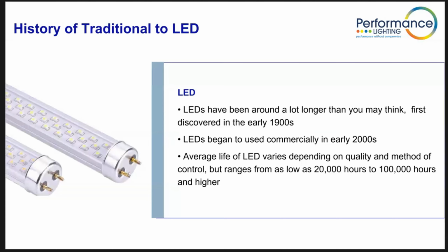A slightly new feature, and we won't really touch on it today, in relation to colour temperature, is tunable white, which means you can actually change the colour temperature. It's one LED, and it can go through the colour temperature normally from 2,700 to 6,000. So that's available, and it's fairly new technology, but we could always speak about that in a further webinar in the future. So I guess that's a little bit of background about fluorescent and LED. Hopefully that's been quite insightful.